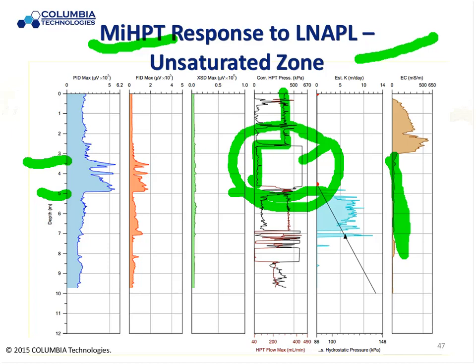Now, if I try to go get that with a monitoring well, it's not going to work for a number of reasons. A, I'm not in the saturated zone of the groundwater region. Second, I'm in a very tight soil, so my mass, this is back to that remedial design characterization. If I want to clear my mass off the site and get rid of this lingering, repetitive groundwater that keeps coming up with a very low level amount of dissolved phase material, I'm going to have to go after this source, and it's going to be in this tight grain zone. So this is how you can target your dollars in technology and resources as opposed to trying to get the groundwater to give you the answer. So it's just like a sponge.